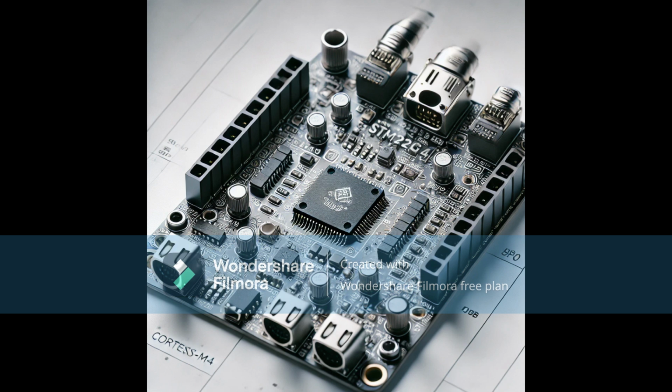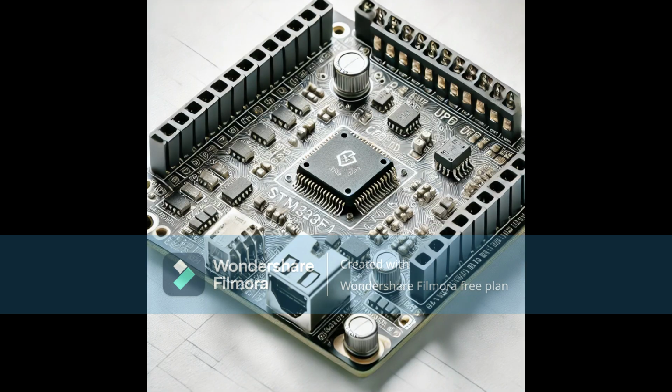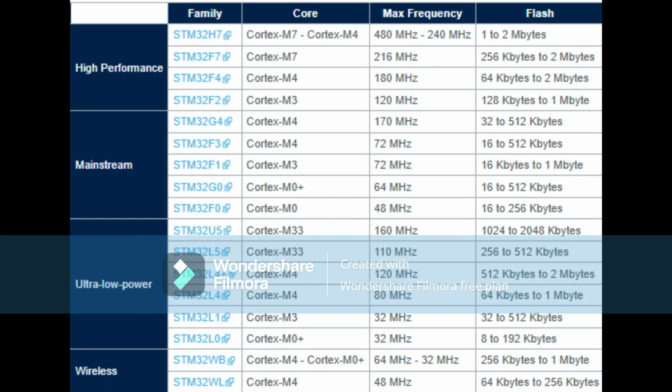STM32L1, Cortex-M3, 32 MHz, 32 to 512 KB. STM32L0, Cortex-M0 plus, 32 MHz, 8 to 192 KB. Wireless: STM32WB, Cortex-M4 and Cortex-M0 plus, 64 MHz and 32 MHz, 256 KB to 1 MB. STM32WL, Cortex-M4, 48 MHz, 64 KB to 256 KB.